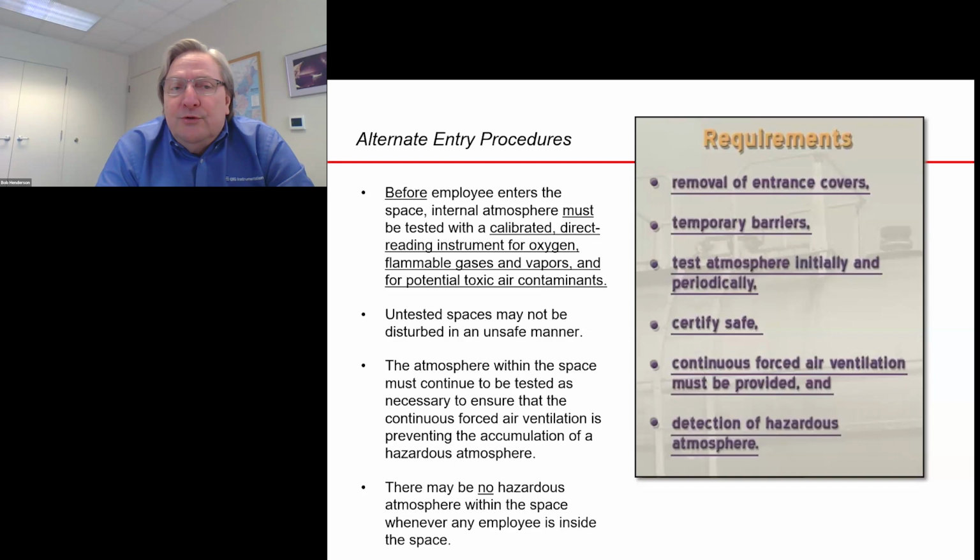So here's how you do it. Before the employee enters the space, the internal atmosphere must be tested with a calibrated direct reading instrument for oxygen, flammable gases and vapors, and potential toxic contaminants.